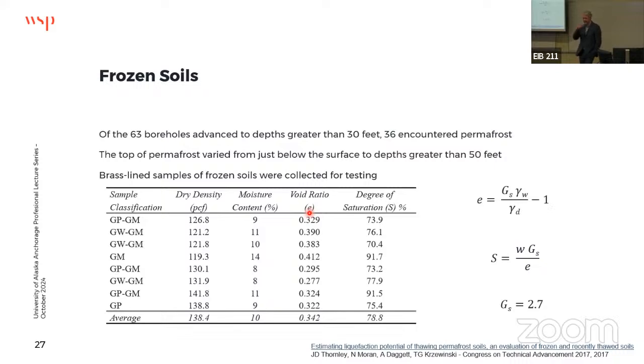And I will say, we have some soils called thaw stable soils, right? Say you do pile design. In pile design, we have a definition for thaw stable soils that we don't have to deal with if the soil thaws. The whole concept behind thaw stable soils is they don't have the moisture content to spread apart the particles, and you end up with densely packed particles, right?